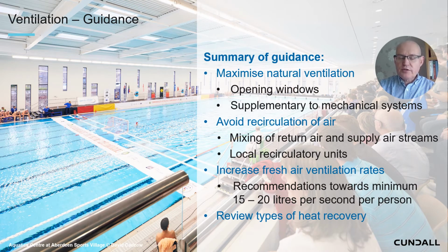Firstly, a lot of emphasis has been placed on the use of natural ventilation where possible. Secondly, avoiding recirculation of air where possible. That's avoiding the mixing of the return air stream into the fresh supply air, and also looking at local units such as fan coil units, which can recirculate air locally in spaces. The possibility of increasing fresh air ventilation rates.